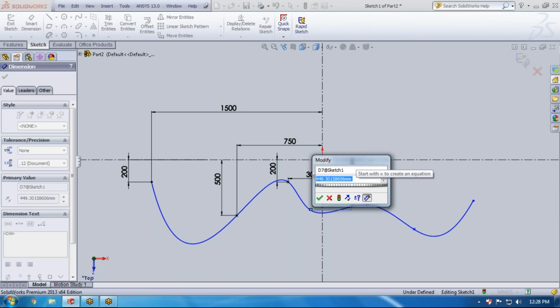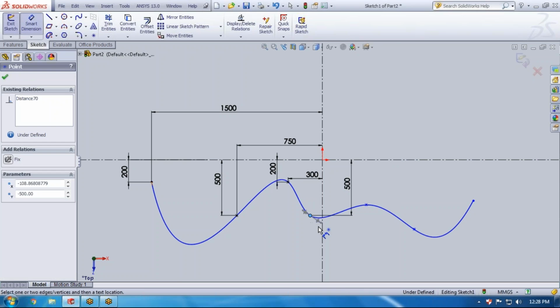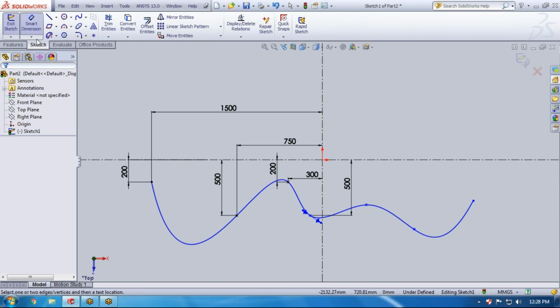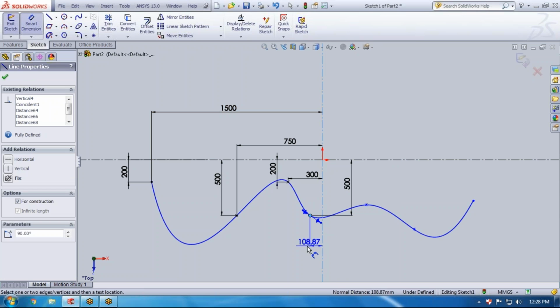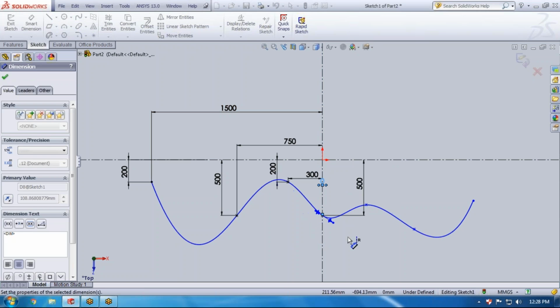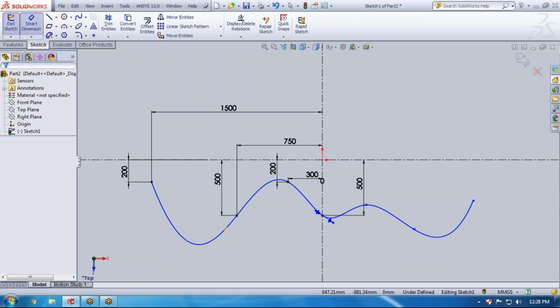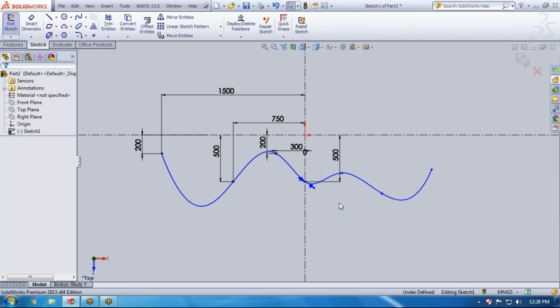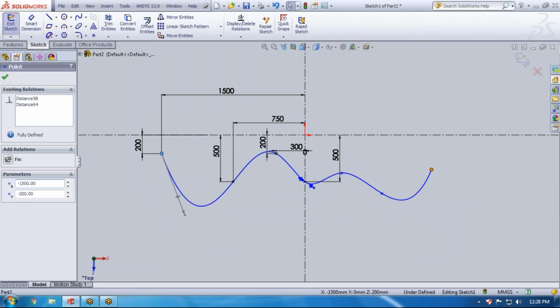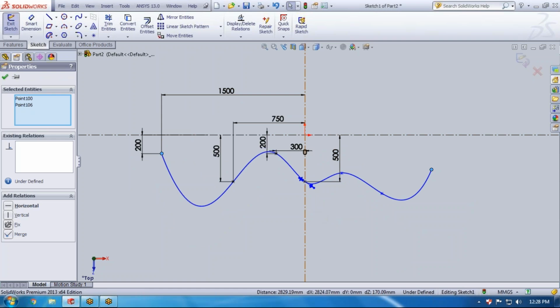Now what I'm doing here, this point should be assigned with this line. I'm giving the distance as 500, and after that this one should be, wait a second, 1, 2, this distance I'm giving 0. So this is at the center. Now I'm making the line totally symmetric. So go for point 1, point 2 is this, make it symmetric with respect to this vertical line.